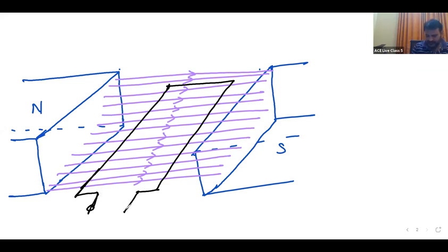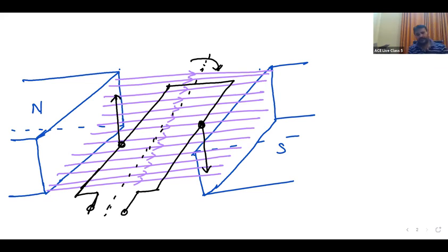It will be connected with a resistive load across the coil. EMF will be induced in this coil, right? Yes. And the coil is rotating. This side is rotating in upwards direction, and this is moving in downwards direction. So that coil is said to be rotating in clockwise direction. Correct? Therefore, one side of the conductor is moving upwards, the other side of the conductor is moving downwards.